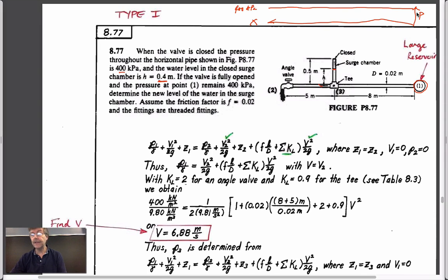And since it's fed by this 400 kPa pressure in this container, by definition, you could use Bernoulli on this. The velocity here is 0, the velocity here is 0, the elevation of these 2 points is 0, therefore the pressure drop along here has to be 0 as well. There can be no head losses, right? Because there's no velocity in the system. All of our head losses are a function of velocity. So the initial pressure all the way through the system is equal to 400 kPa.